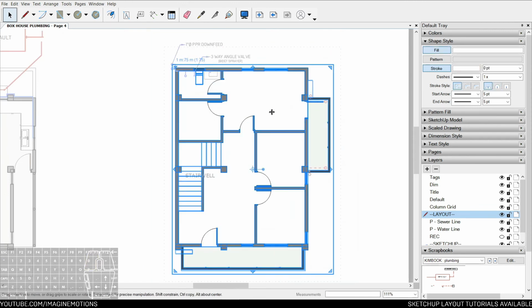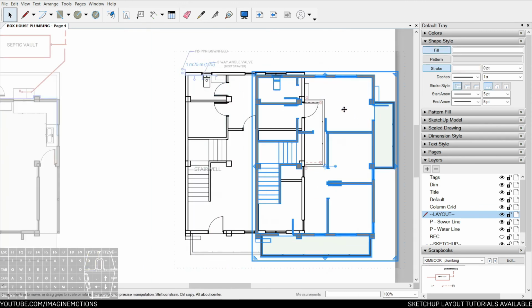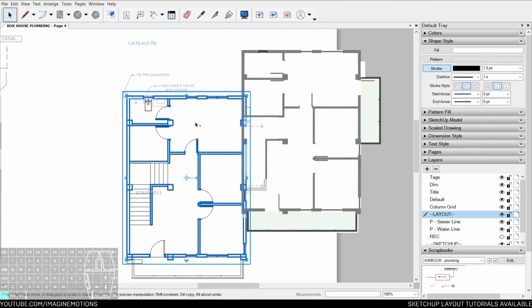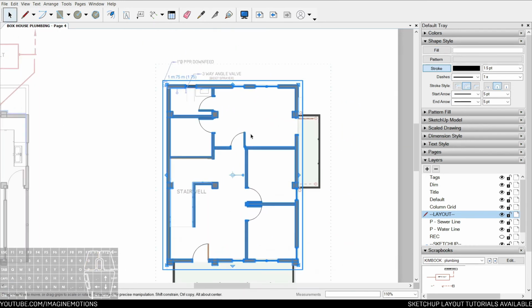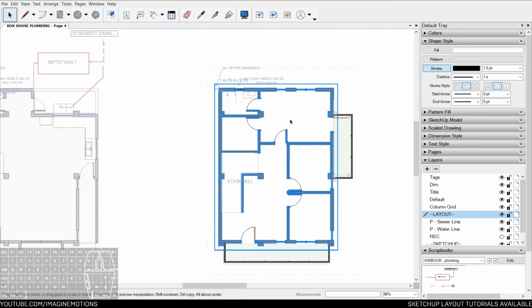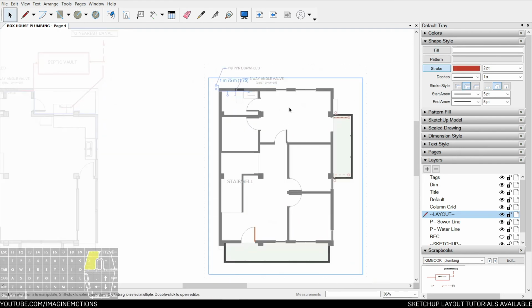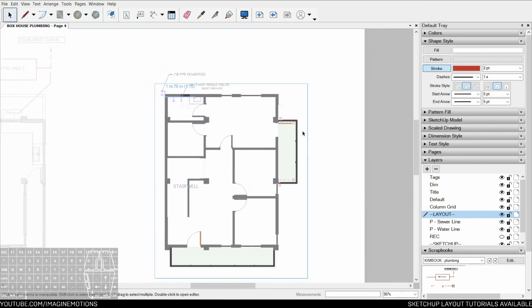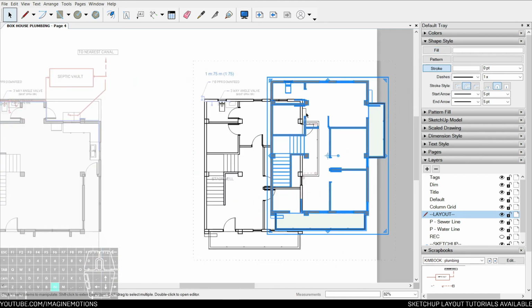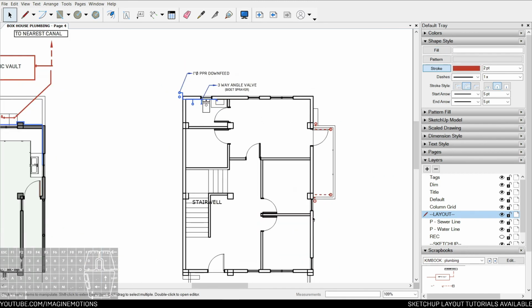Once you go into that group, you might have two kinds of drawings, the fill and the stroke. This happens when you are in raster or also in hybrid mode. In hidden line, it might be transparent. So I'm going to select the fill and delete them. Yep, this one. I'm left behind with a hidden line style.